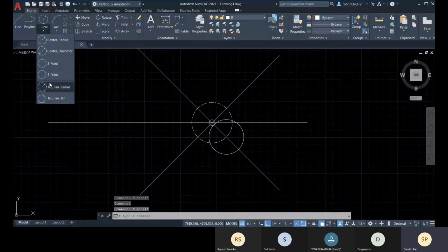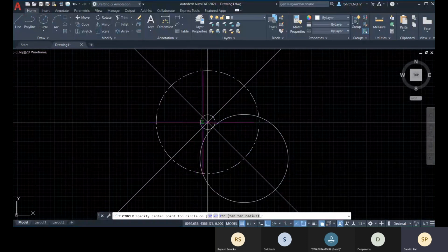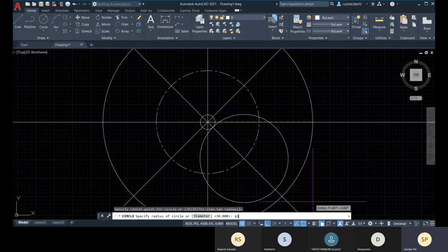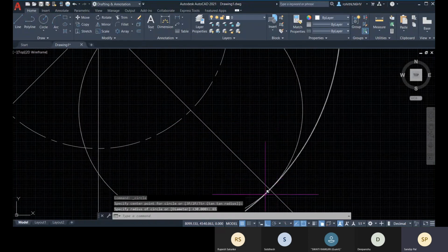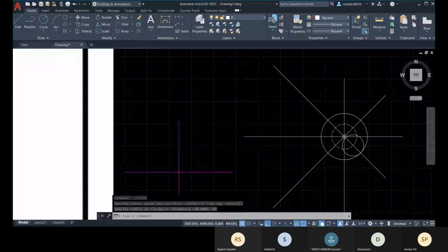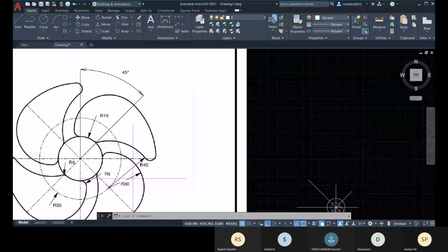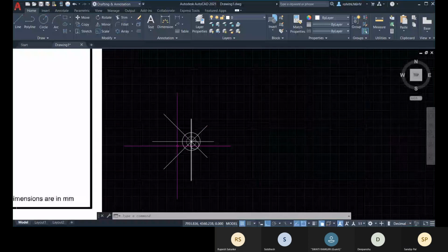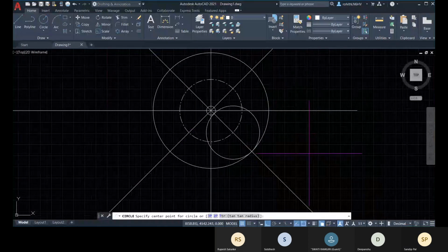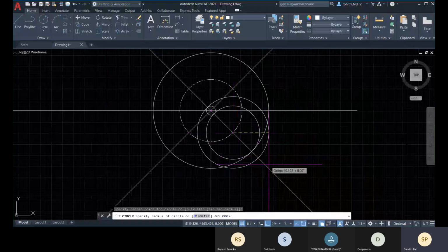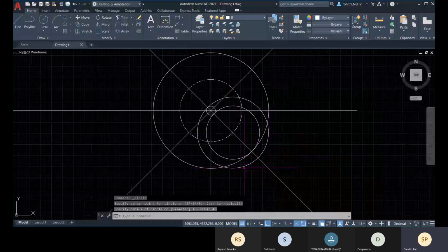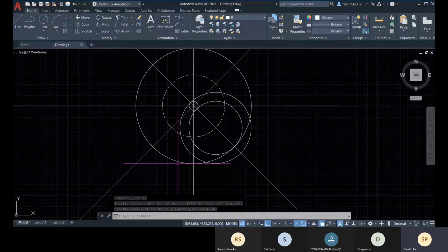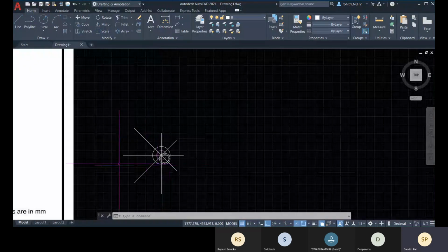So you can understand that for the 65 circle, this is the center, and you specify 65, enter. Right now you can see, right? You have that. Okay. And about the radius 40, go for it. This is the center, and that is 40, enter. Okay, that you have created. And now what you have to do? You have to fillet it.